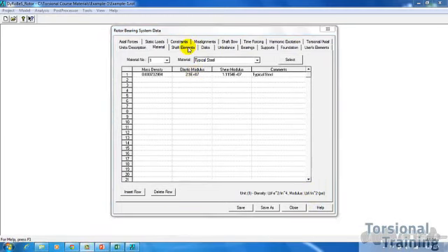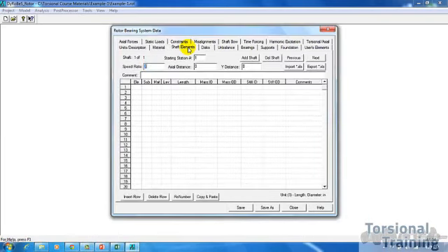And after selecting the material, go ahead and now click on shaft elements. And this here is the meat and potatoes of Dyrobes. This is where you build your rotor. Dyrobes follows a sort of a finite element approach. If you've had any experience modeling using ANSYS, then think about what you do. You select your units, you select your materials, and then you do your pre-processing, build your model, and then you assign your elements. So we're sort of following the same basic approach.